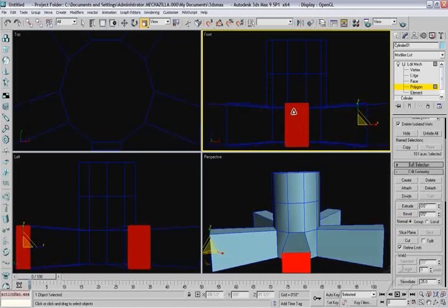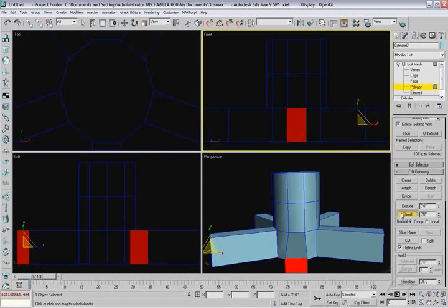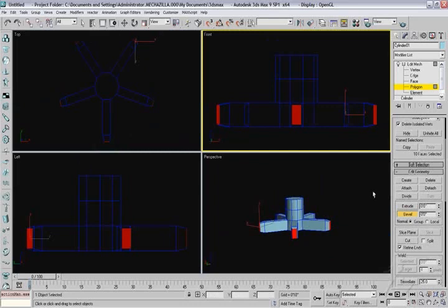Oops. Try that with the bevel on and extrude out just a little bit. Let go of my mouse button, it becomes a scale function. And looking in the front viewport, I'm only going to go about a quarter of the way in, and then left click to end the bevel function. And then I'm going to hit my zoom extents all button. Now you'll notice here when it did the bevel, it tapered upward.